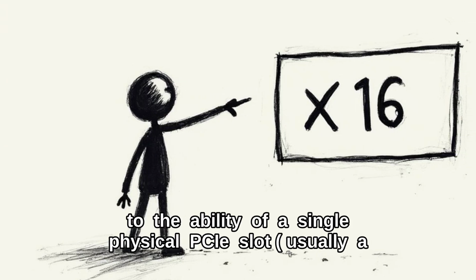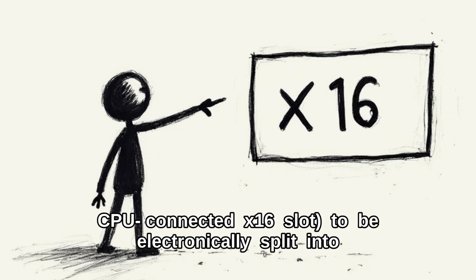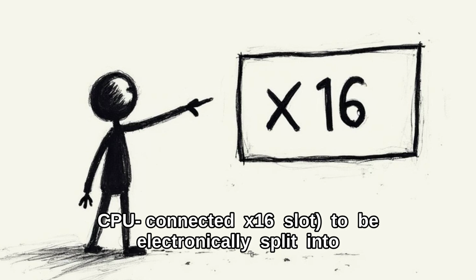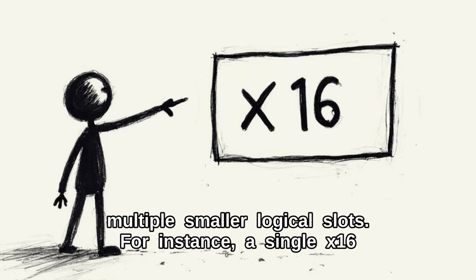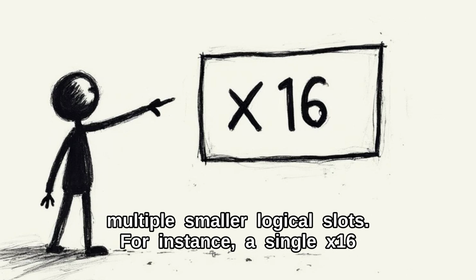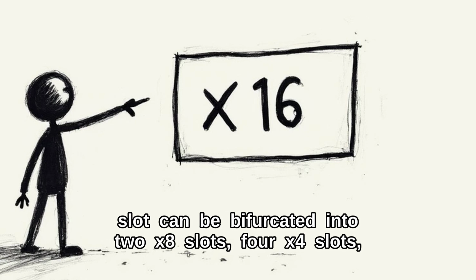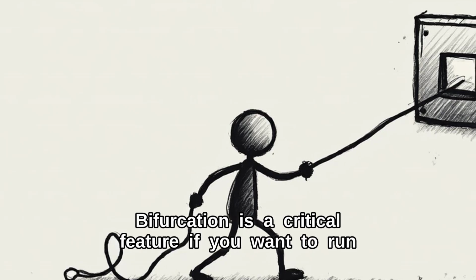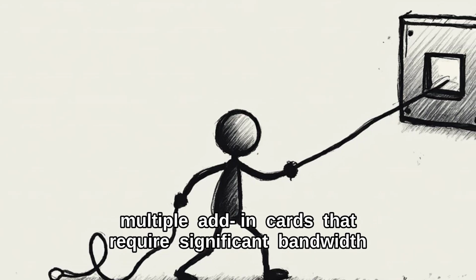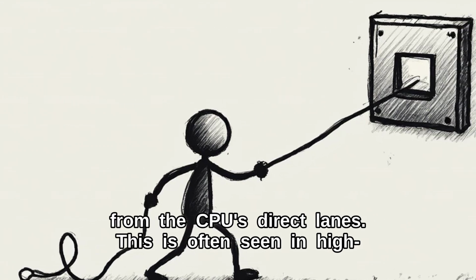Now let us talk about bifurcation. This term refers to the ability of a single physical PCIe slot, usually a CPU-connected X16 slot, to be electronically split into multiple smaller logical slots. For instance, a single X16 slot can be bifurcated into 2 X8 slots, 4 X4 slots, or even 1 X8 and 2 X4 slots. Bifurcation is a critical feature if you want to run multiple add-in cards that require significant bandwidth from the CPU's direct lanes.